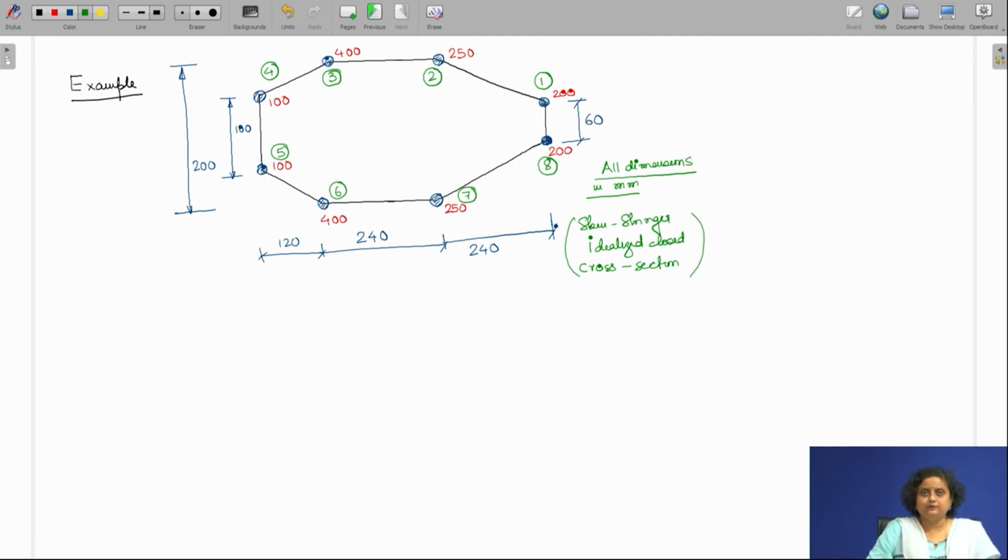There would be no difference in the process of finding the shear flow in a closed cross section beam. The only thing that would be different is that because the shear flows are going to be constant in each of these portions, the calculations will become extremely straightforward. So, let me write down the problem statement.